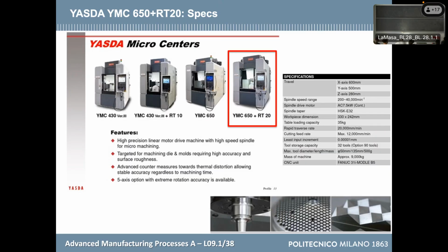Or if I speak in microns, in this position there is the micron. So it is 1/100th of a micron. So I can tell my machine, go ahead by 1 step of this dimension. And it does that, it controls that. I'm not saying that we can do a part with that precision, but I'm saying that the machine controls that. Then I have to sum all of the other uncertainties I have. But if you start from there, we have also done parts at micron-level precision.